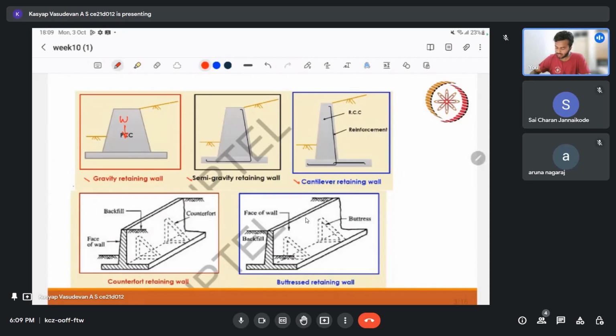So hence its cross section is very big. After introduction of steel, we reduced it a little bit. We were not confident much in the beginning. So if you want an adaptive design, we can go for steel, and it will drastically reduce the cross section area of the material requirement, whether it is masonry or steel or concrete. It can be reduced by providing steel as a reinforcement, because since earth pressure is acting like this, our